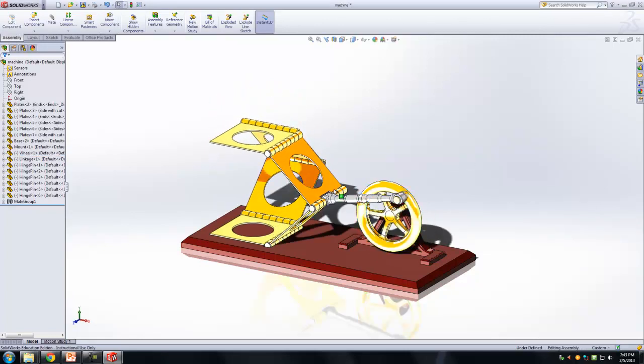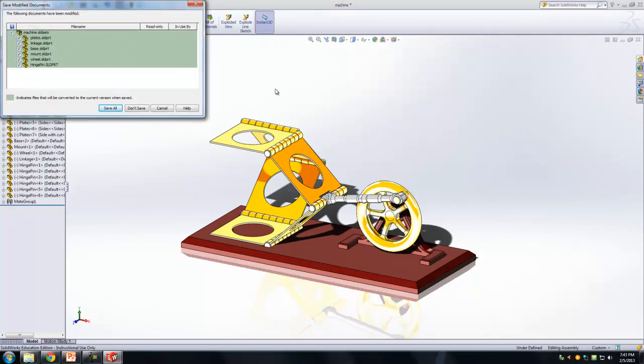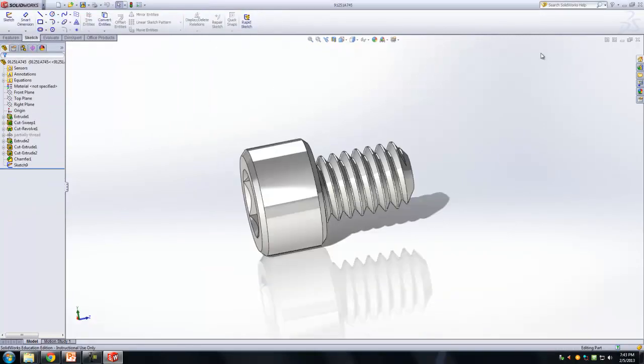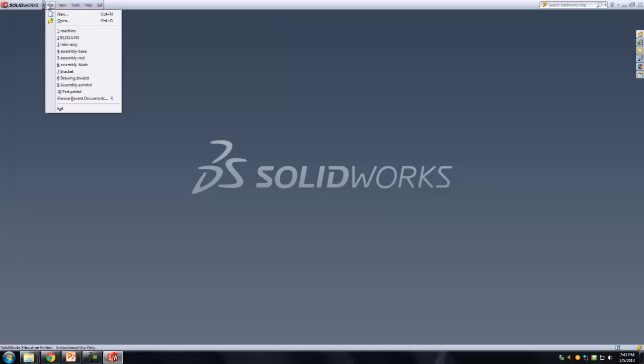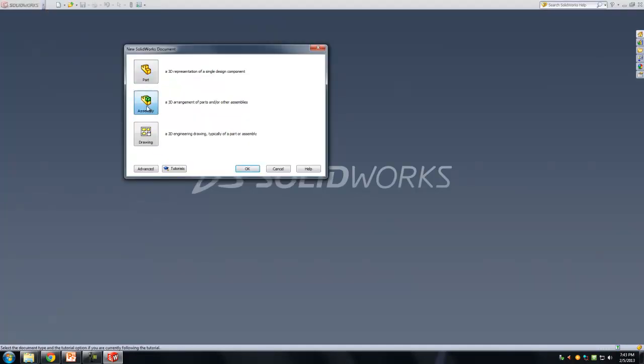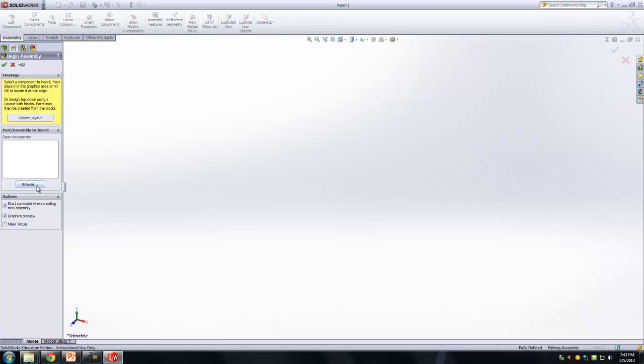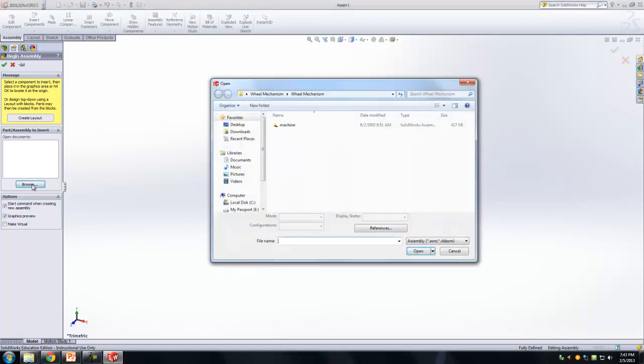So we're going to go through something like that just to remind you of how to create assemblies, but you should know how to do some of these things. I'm going to show you some additional hints that we didn't talk about before, but then we're going to open this up and create the ballooning in a drawing setting. So for now, I'm just going to go to File, New, Assembly. So File, New, Assembly, and I want you to import by simply clicking Browse, import the base.